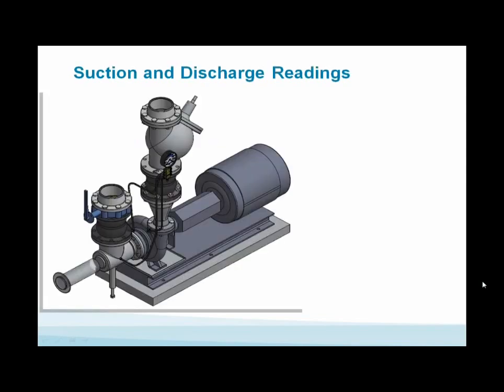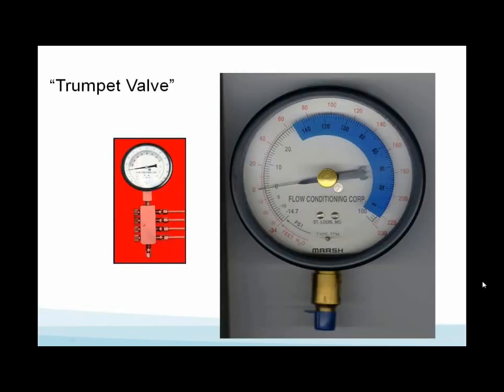So I got a pump. I want to read the differential pressure across the suction and discharge tappings on that pump to see where it is on that pump curve. So our pump is generating 63 feet of head. Differential pressure across the pump, when I just turned it on in that system, is 63 feet of head.